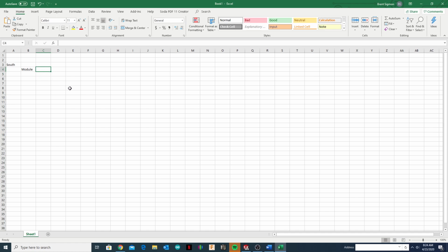I'm going to do my modules. I'm going to do 345 watts. I'm going to choose the number of them. So if I'm doing the south facing, I'm going to have 21 of them. I'm going to do my inverters over here, and I'm doing the IQ7A. And I'm also going to need 21 because you need one module for each inverter.